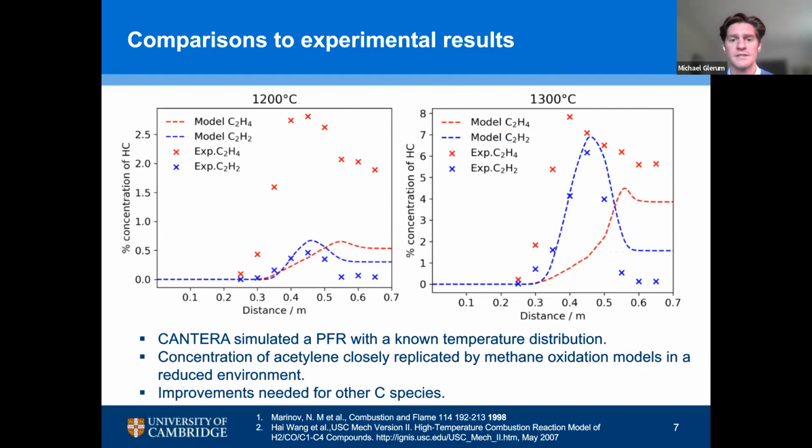One of the first things that we did was to actually measure the constant species distribution as a function of reactor axis. The way we did this was by extrapolating FTIR measurements from our hot furnace, taking measurements at each and every point of the furnace axis.